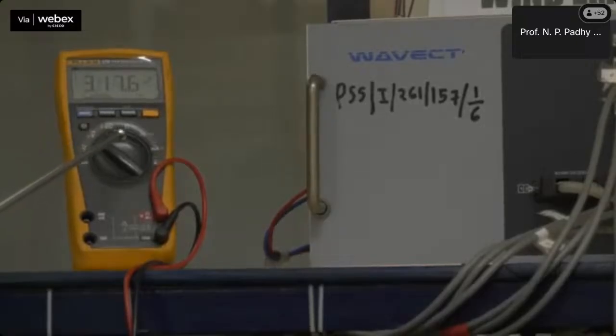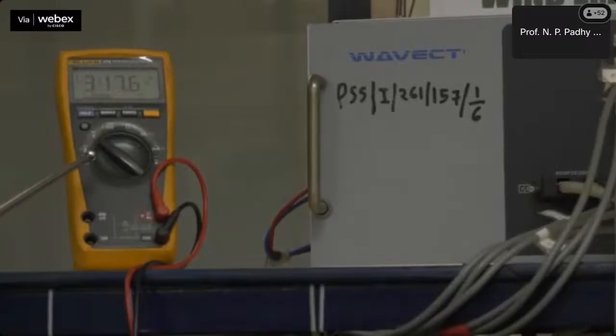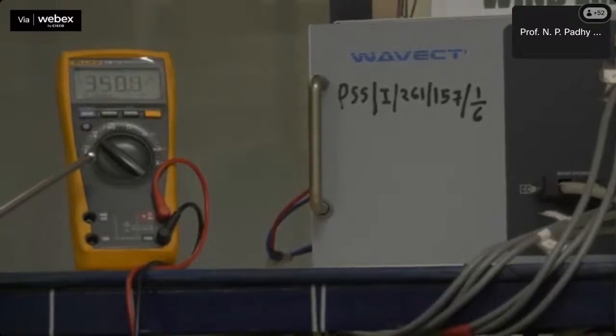Once the DC link is charged, we enable the GSC control to maintain the desired DC link voltage, which is set, say, 30 volt greater than the DC link voltage, that is 350 volts.